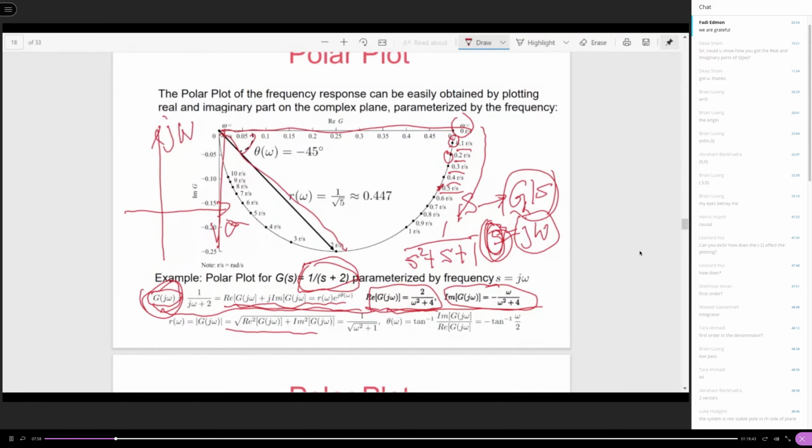We have been talking about this s-plane all the time in Control One: the real part, the imaginary part. So we know how important the imaginary part j omega is going to be. If I look at this plot as a mapping from s to G of s, restricted to s equal to j omega, then this half corresponds to this part. Does it make sense?